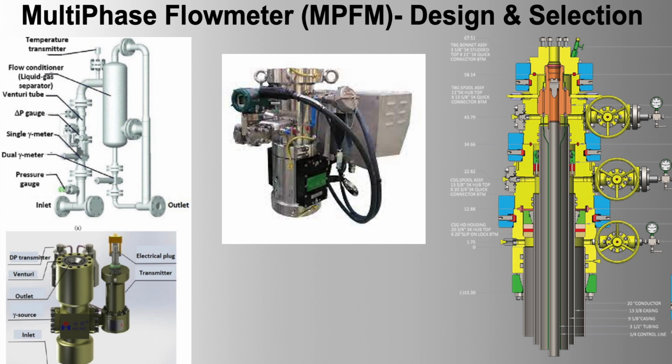2. Operational efficiency. Reduced need for test separators. By eliminating or reducing reliance on test separators, MPFMs simplify the infrastructure and reduce maintenance. Continuous monitoring. Continuous, uninterrupted flow measurements help in identifying and mitigating issues quickly without shutting down the wells for testing.